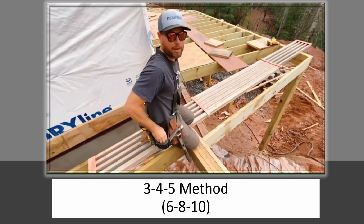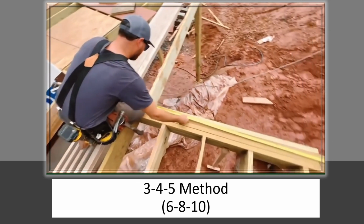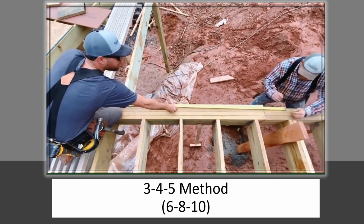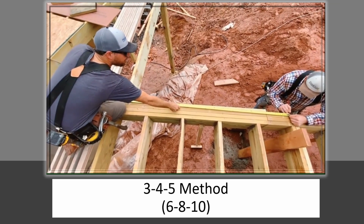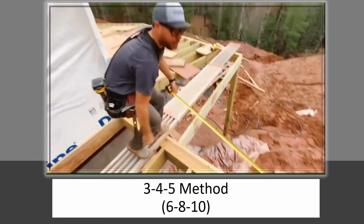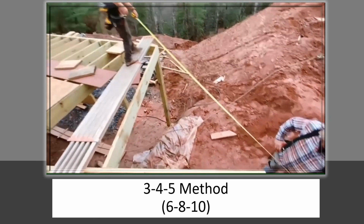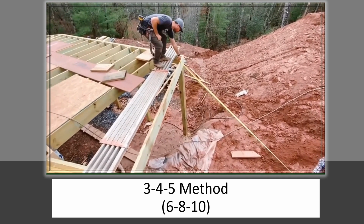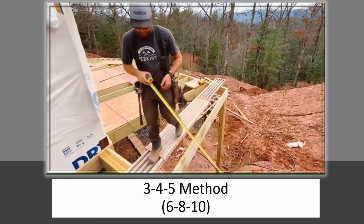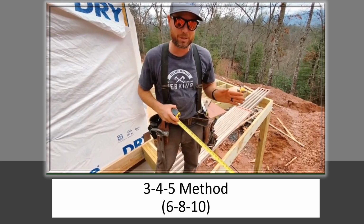All right, now I'm going to make my mark again 6 feet this way. All right. Now let's check our diagonal again, see if it's 10 feet now. All right, that's bang on it. So we have adjusted this piece to where we have a perfect 90-degree angle coming out of here, which is what we want because the decking will look good.